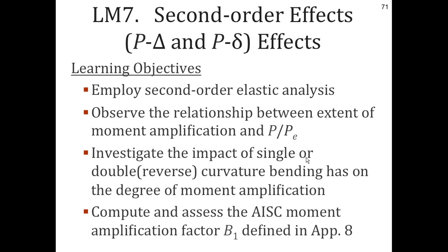Learning Module 7 is a neat one. It has an in-depth look at second-order effects, so not only the P-capital-delta effect, but this P-small-delta effect. And pay a lot of attention to this B1 factor. And in fact, Dawn's going to talk about it next week.